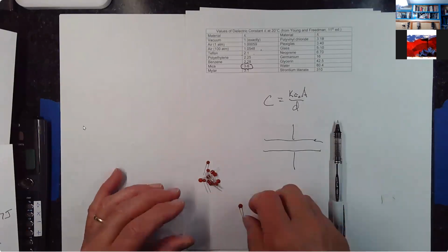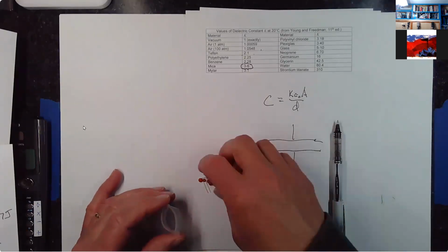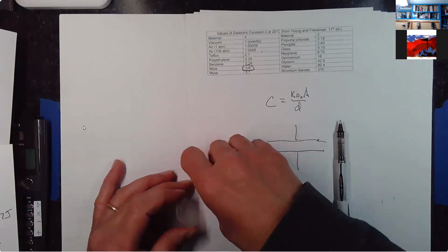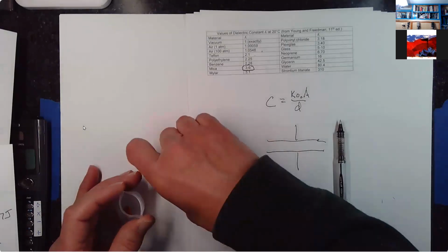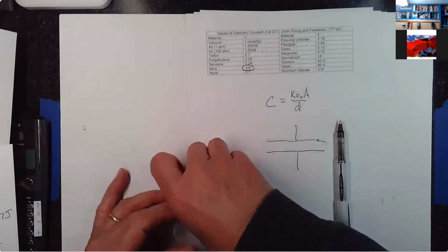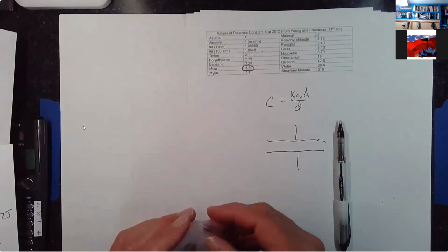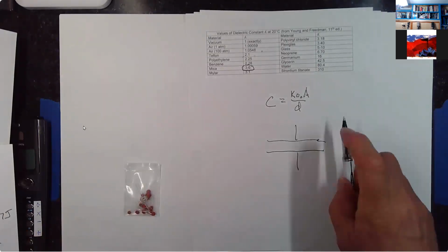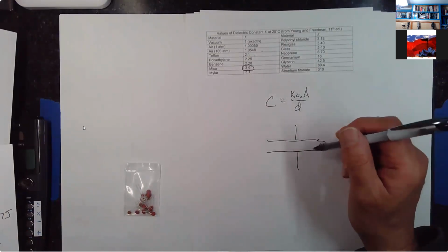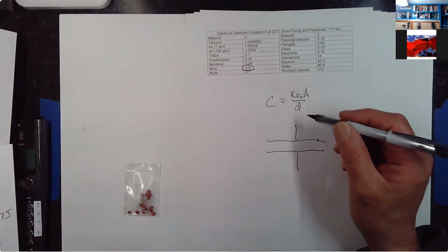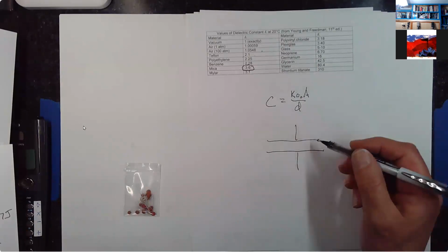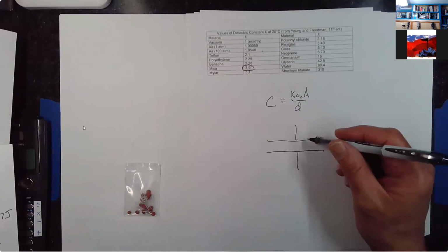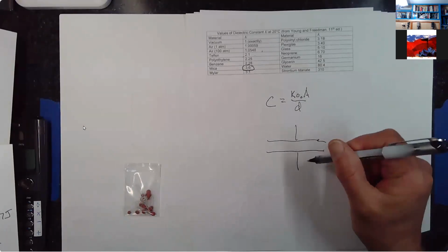One thing they do is if you've got an alternating current circuit, they'll have particular properties in there that become advantageous. But if you've got an alternating current circuit and you accidentally get some direct current in there, the capacitor will kill that direct current because you can't have current flow across these parallel plates.